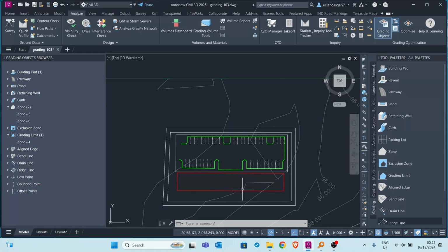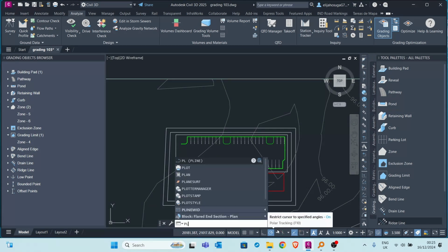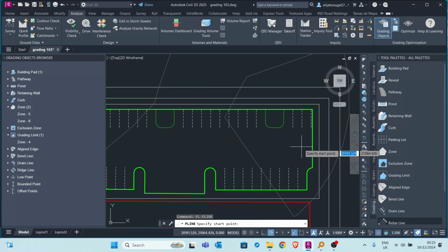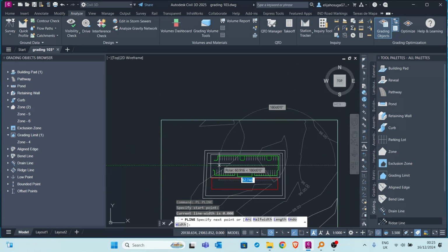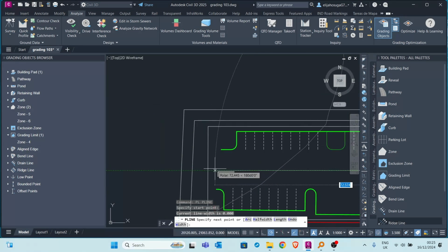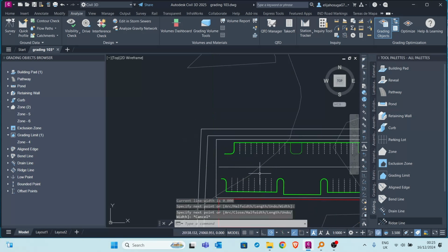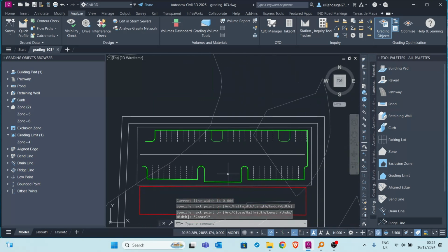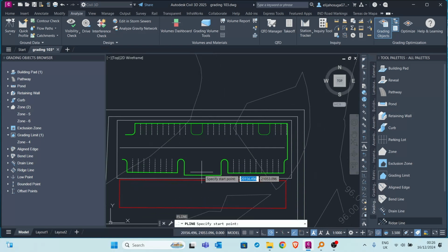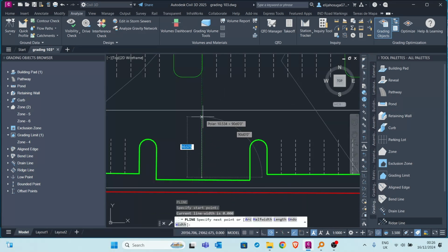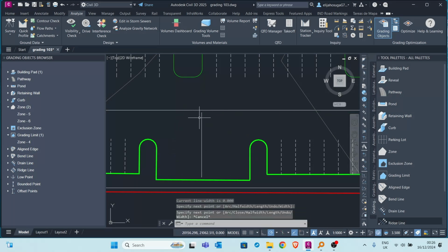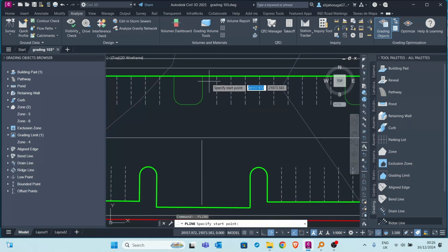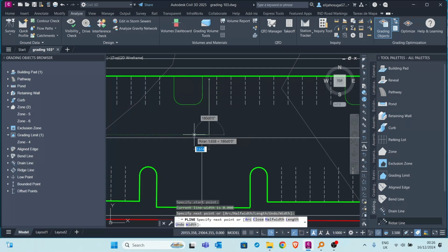We also use polylines. So let's create polylines that show our drainage. So polyline again. Start where the flow is starting from and where it's draining to. So you start from this side and then it's going to, let's say, drain on the road outside there. Then let's draw another one, flowing also away from the building, coming to meet the other flow path. And also another one draining from this parking lot, coming to the center and then flowing outside.